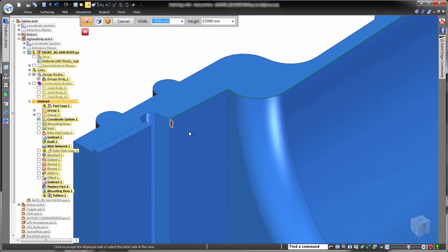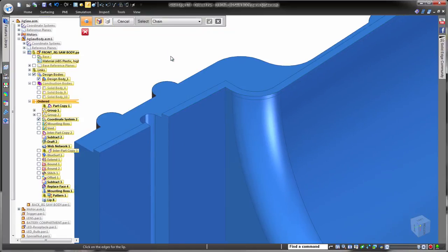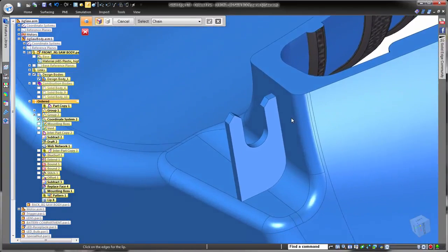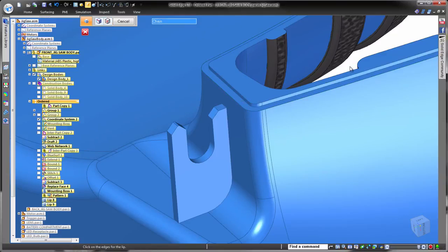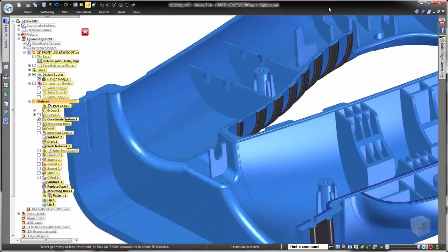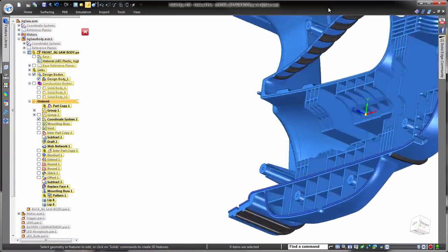Notice that as we simply move our cursor around, we can change the location of the profile and therefore specify creating the lip above the edge. As we pan to the center of the handle area, we'll generate the same dimensional profile, yet by simply adjusting the location of the profile into the part, we can quickly generate the complementary groove below the edge.